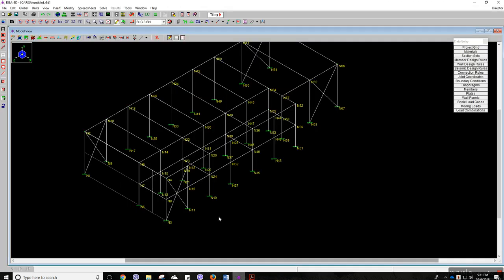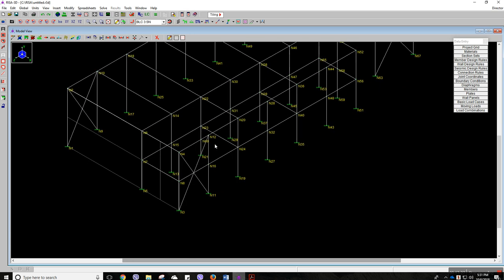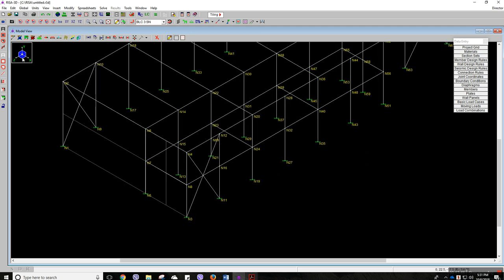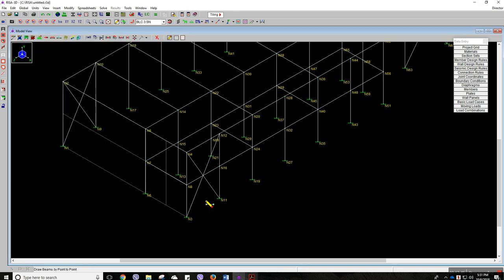Even though we know we are going to apply that one, we don't know where the 2A line, the 2A point is. So let's draw the 2A point first. As we know, the 2A point is 13.2. I told you that earlier, right? It is 10% of 66 is 6.6, times 2 is 13.2. Okay, let's go and make a point here at 13.2. First, let's draw a member. We are going to delete that one.